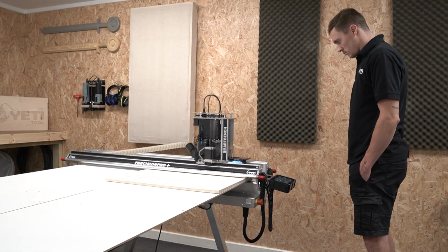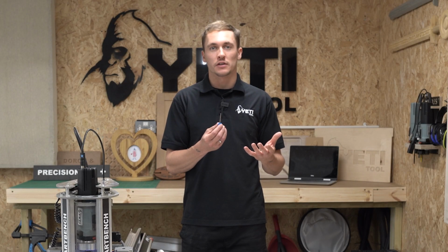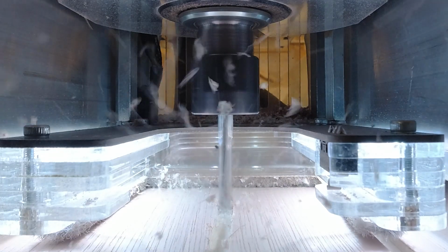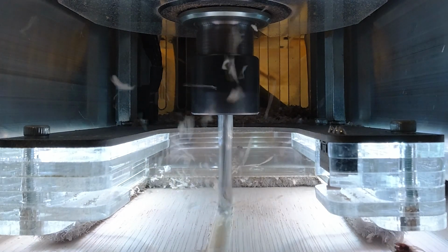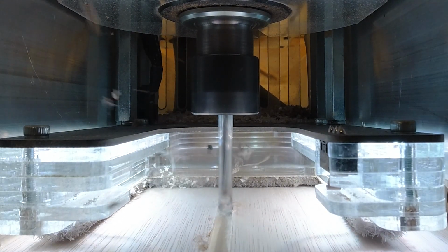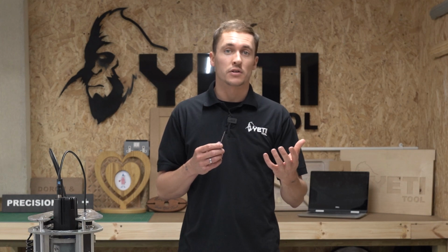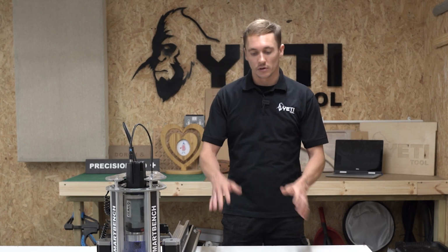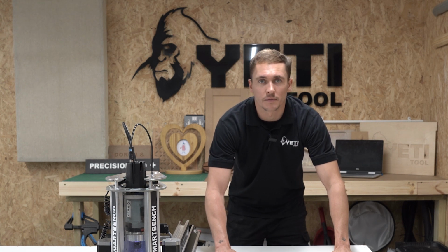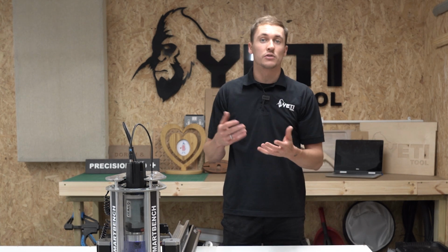For example, let's say you're using a small 3mm cutter like this one for some detailed work. These cutters are not particularly strong, so if you set your motor load too high, you're likely to see some cutter deflection, which can lead to inaccuracies in your cut. To increase accuracy, you want to set a lower target spindle load. This is to ensure that YetiPilot isn't going to adapt your feed rate too high and cause excessive cutter deflection. If you're looking to optimise your cutting time with a stronger cutter or on a softer material such as poplar plywood, then you can experiment with increasing your target load.